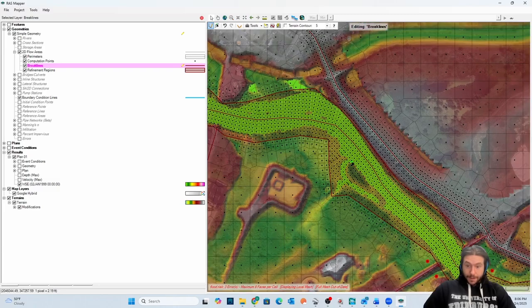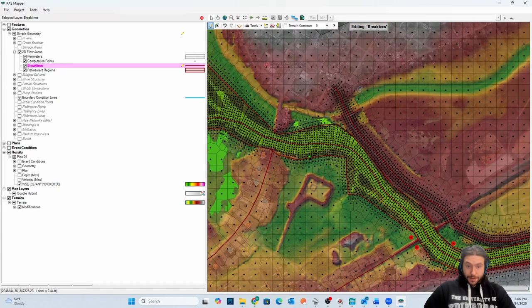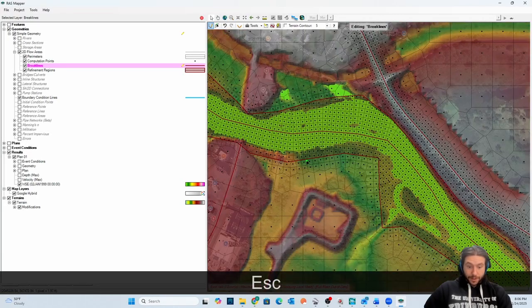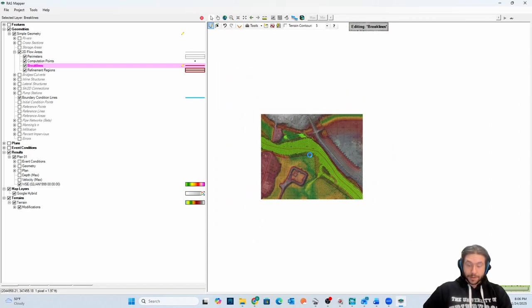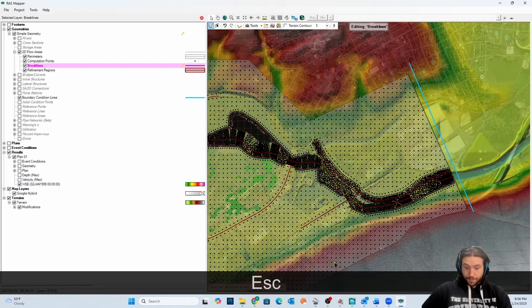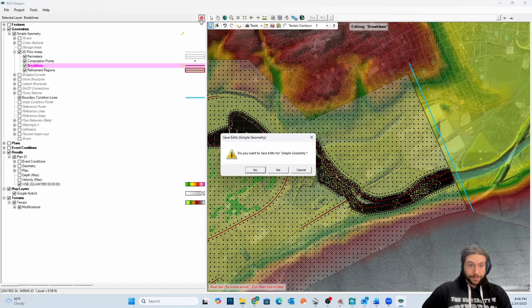Actually, again, since I've had pretty decent compute times, I'm going to decrease this size even smaller, because normally you would decrease it smaller. Even this external area is quite large for a real model. With increasing complexity, you want to slowly refine your model down so you get smaller and smaller sizes, longer run times, but better results. But since we're getting closer, I'm okay with a little bit longer run time.